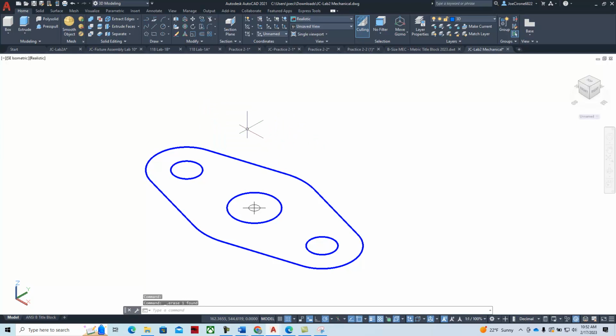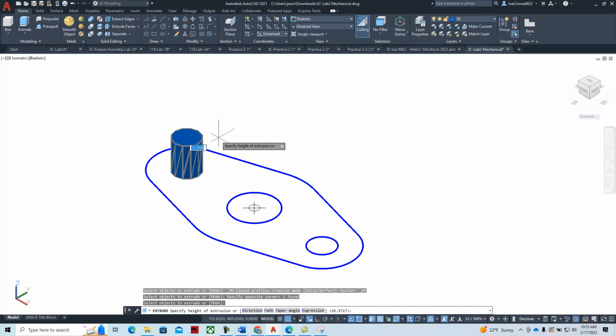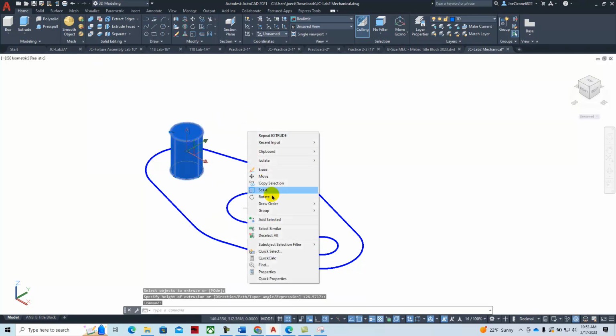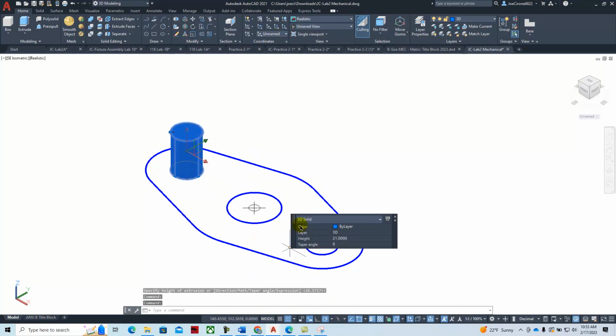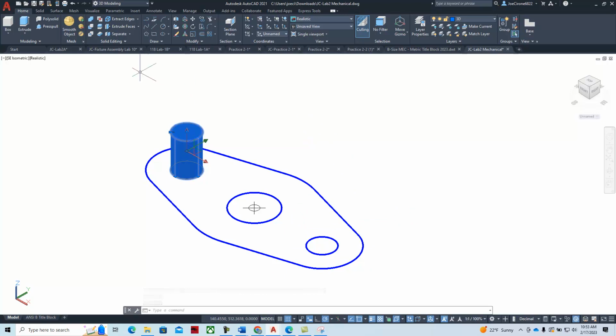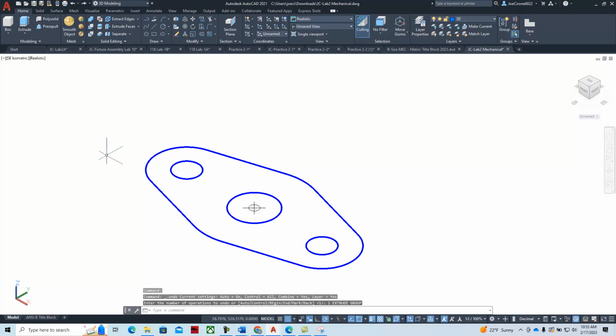If you use the straight up extrude command, you have to have a closed polygon or boundary shape. So if I were to extrude the circle, since that's a closed shape, this would be a solid. And that's 3D printable, and we can do things like Boolean operations like subtract on it. But if you just straight up extrude it, you'll get a surface.